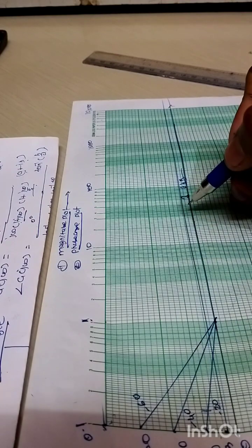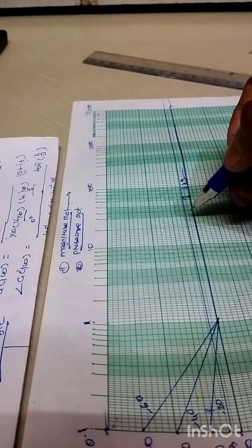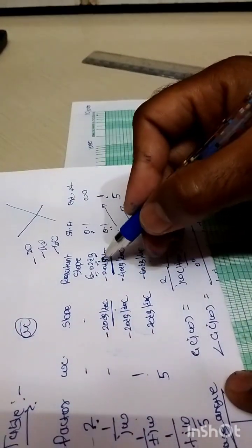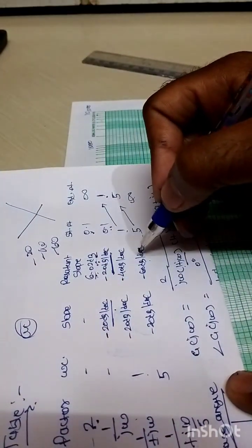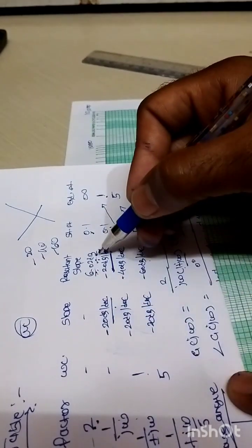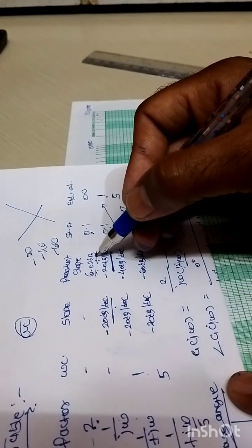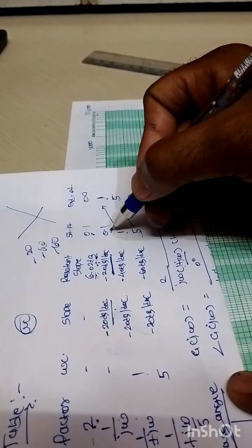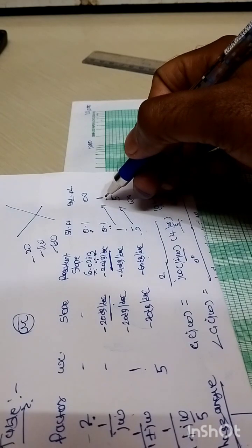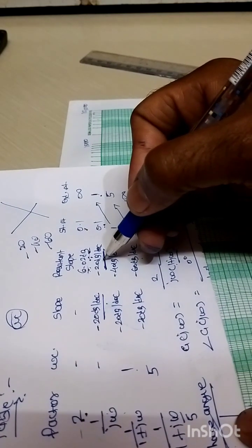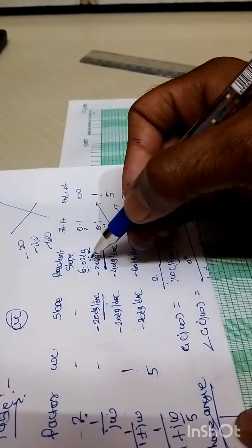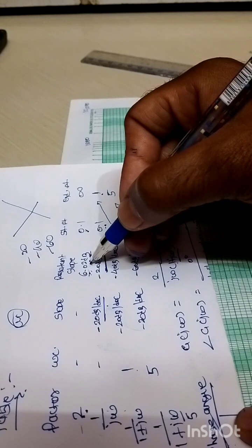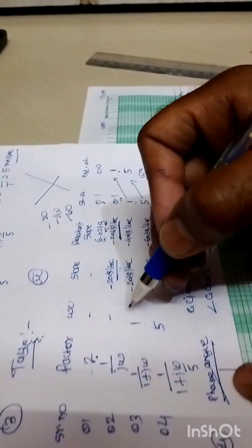So this is the 6 dB line, right? Whenever we are considering the remaining factors, they are to be drawn after the 6 dB line, right? Means this 1 over j omega is being treated after the 6 dB line. So this 1 over j omega starts at 0.1 radian per second, ends at 1 radian per second with the desired slope of minus 20 dB per decade. But the important thing we need to note is it will be started after this 6 dB line, right? Because this is the second factor.